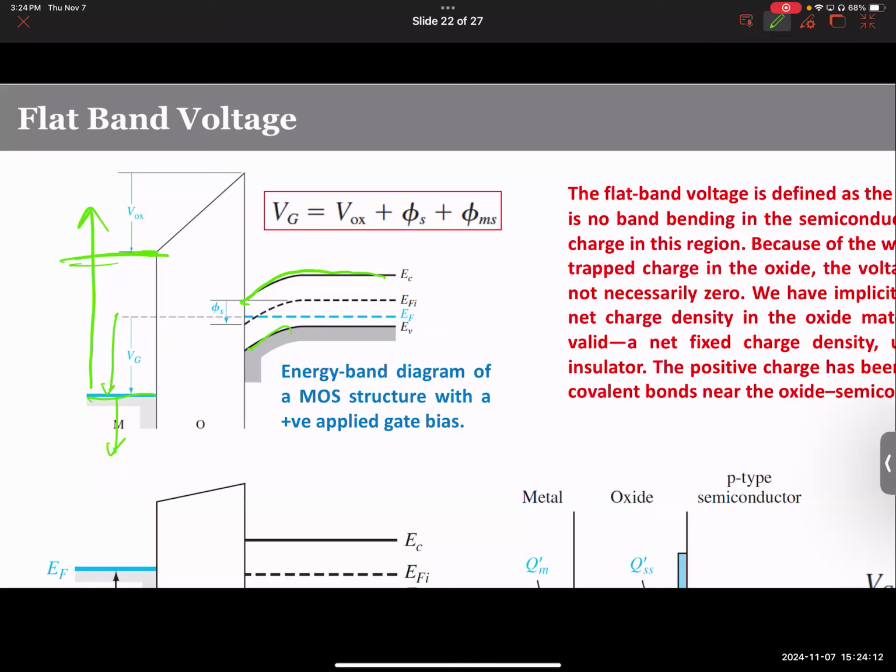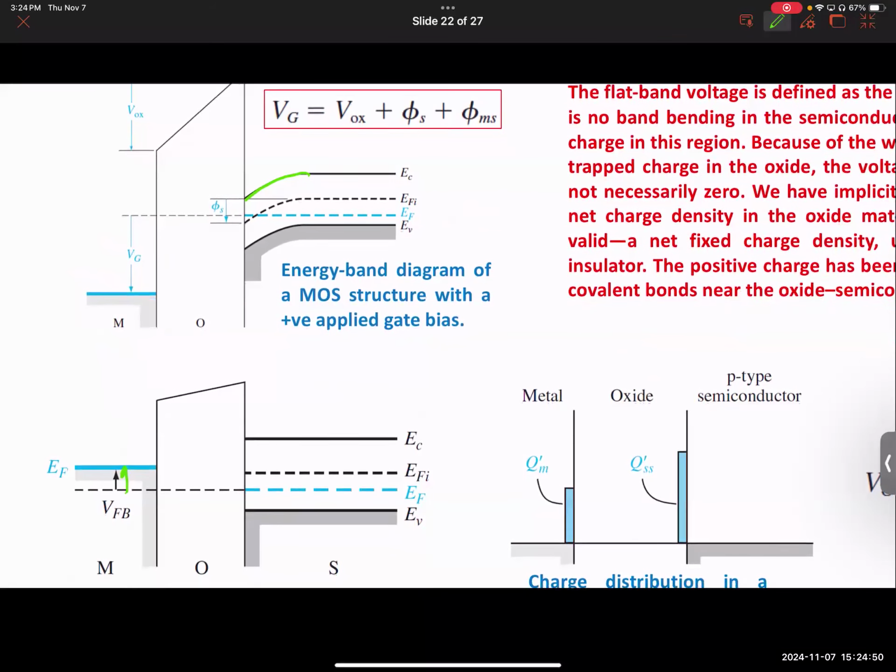And I'm fast forwarding, but I seriously hope that you remember that. Remember, I use this analogy of when you apply negative voltage as if you have a helium balloon. It takes up the Fermi level, right? When you apply positive voltage, you have applied some weight and the Fermi level goes down. To help you remember, the same concept applies here. It didn't change. So basically, when you apply negative voltage, the Fermi level will go up, and then these bands will start following the direction of the applied voltage. So now that it is already bent down, to make it bent up, you have to apply a voltage in the other direction so that it flattens, basically.